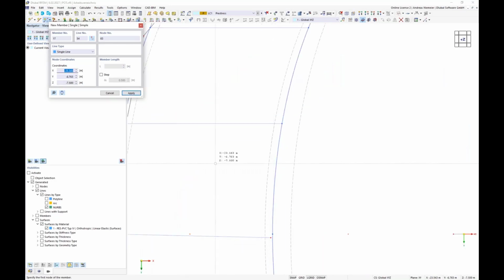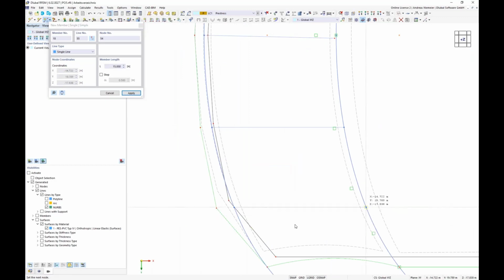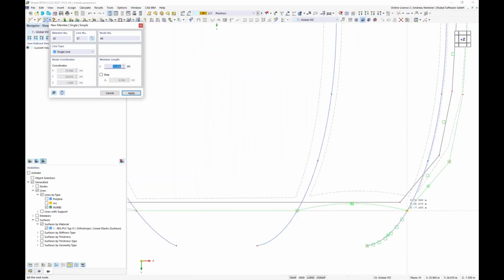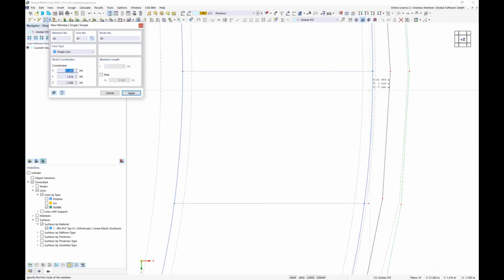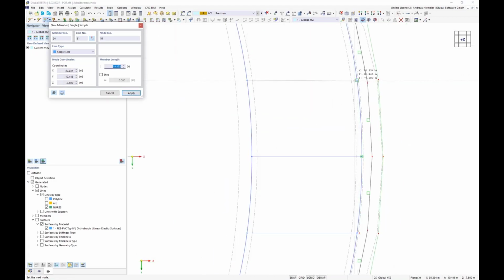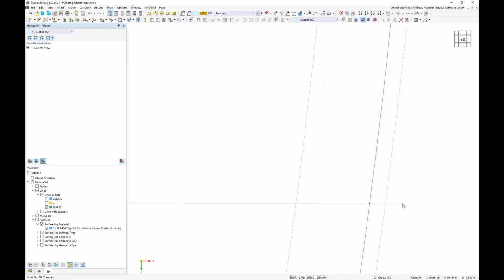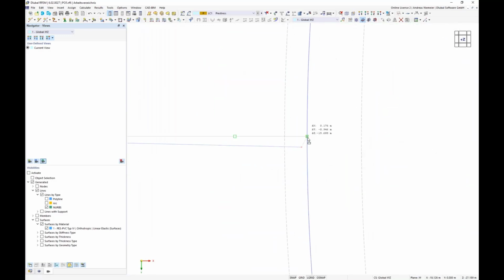now I made an error, you see. Let's correct it afterwards. And also here. And here on the eave left side, now do the same on the right side. And now you see if you found the right node, if the program symbolizes it with such a yellow symbol or snapping point symbol. And now the last one, and then let's correct what we made wrong. So move this node to this situation, and here was also an error, move this node to this situation.